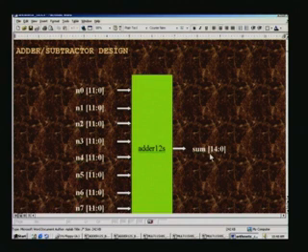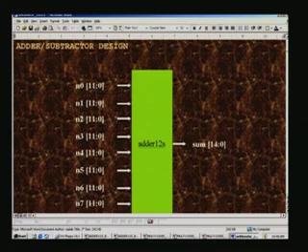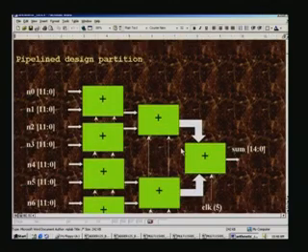We were looking at the design for the adder subtractor, in which we had added 8 numbers n0 through n7, and we got a sum here which is 3 bits more than each of these, and this last bit is the sign bit, so also the case with the sum here. And we had seen that the whole thing was pipelined and partitioned for data width as well as functionality. In this example the functionality happens to be the same, add or subtract, and when we take up bigger applications such as DCTQ, we will appreciate the functionality difference coming in.